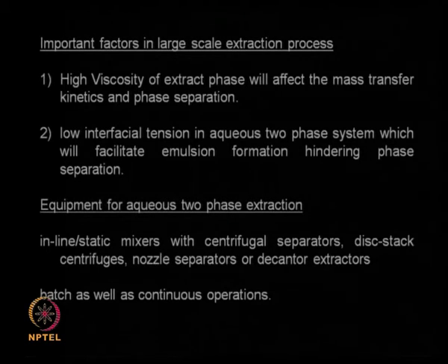So, these two important points we need to consider when scaling up aqueous two phase systems. People have considered inline and static mixers, that means long tubes filled with certain static elements, and when the two liquids flow through them, they get mixed, and hence extraction takes place during the mixing process.